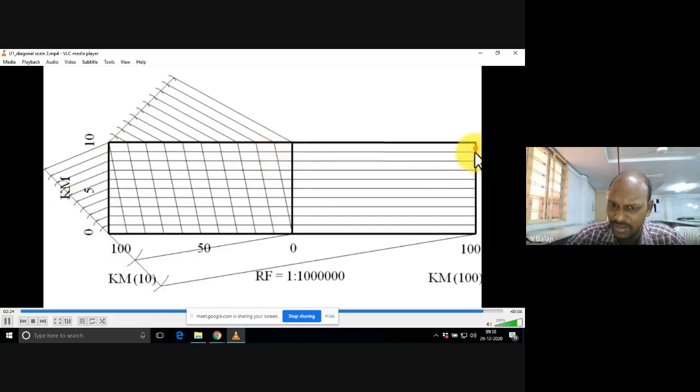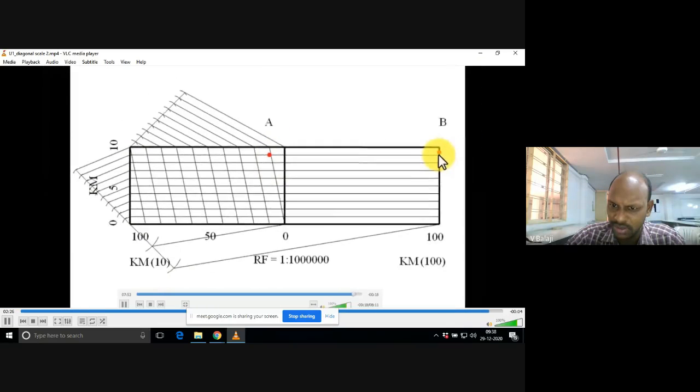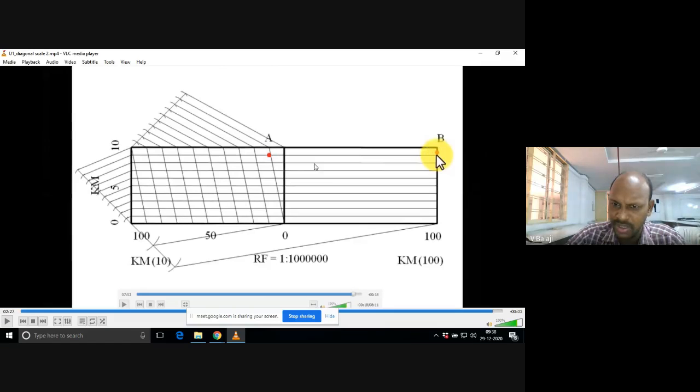109 kilometers, right? Between A and B, you draw two extension lines. In between, put a dimension line on it. The dimension line should be 1 centimeter away from the main rectangular box. Draw on it 109 kilometers, the distance between these two red points.